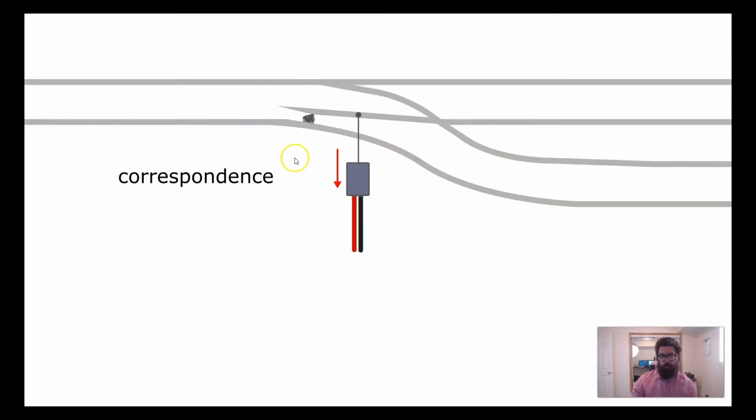Okay, so an important idea when we're talking about switches is correspondence, and that's essentially whether the machine is in the position that it wants to be in. So for example, if we're trying to divert and there's a rock blocking the points from moving to the final position, then it will not be in correspondence. Whereas if it does hit the final position, then it is in correspondence. So you can even be more specific. You can call it normal correspondence and reverse correspondence.